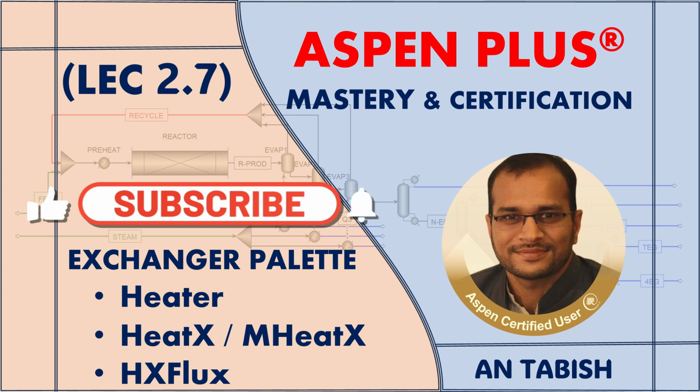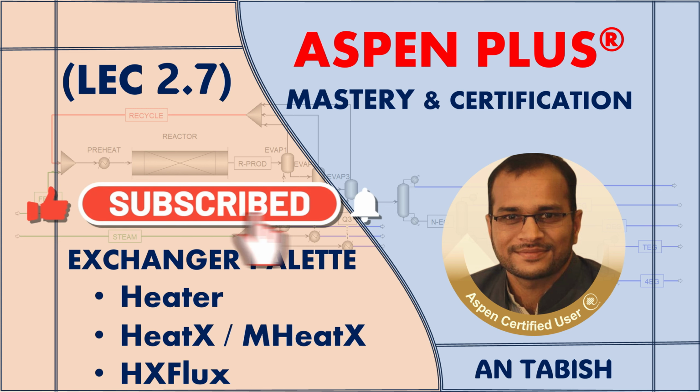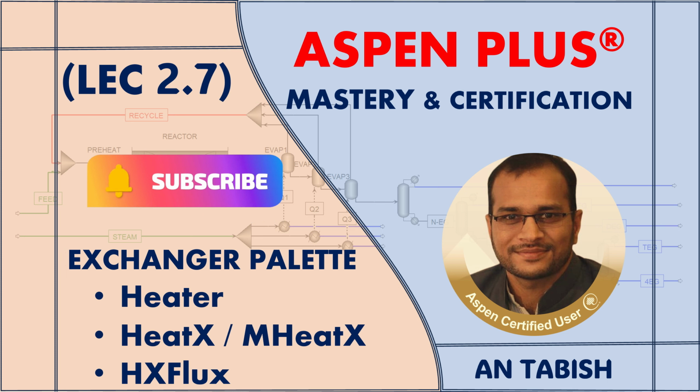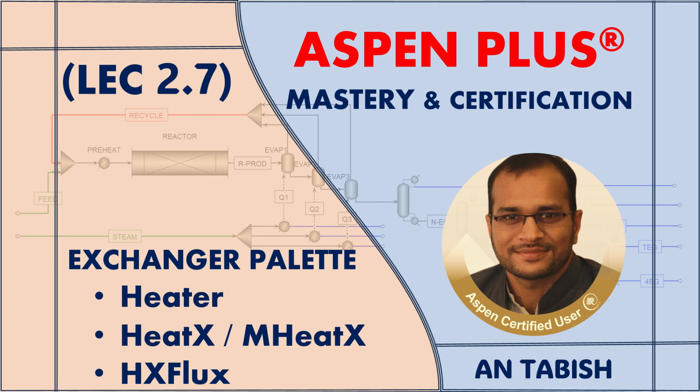The heat exchanger blocks include a simple heater that can be used as a heater or a cooler, a co-current or counter current heat exchanger block that can be used for shortcut as well as rigorous simulation, including rating or design of the heat exchanger. Another block in the heat exchanger palette is the multi-stream heat exchanger and a different block that is HX flux.